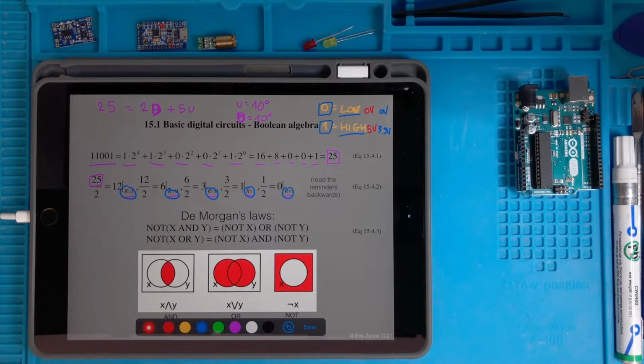So they start thinking how to simplify this, and in the end somebody, I don't know who, had the idea that only two levels of voltage are sufficient in order to do this. So let's go to the binary numbers. We can make two levels of voltages quite distant from each other. The distance can be much bigger than the noise level that might be present in the system, so we are able to identify with some thresholds which are the zeros and which are the ones. And this is why we have this nowadays basically in every computer.